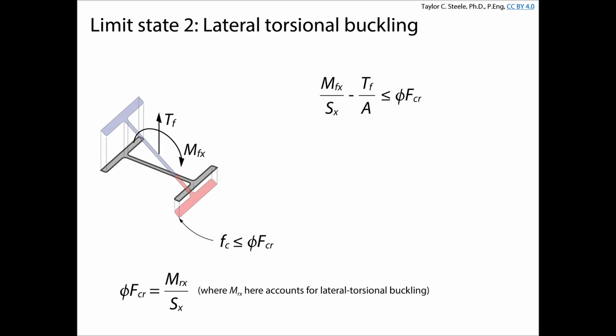Okay, so when we have lateral torsional buckling, we calculate MU, and for a class 3 section we calculate MY, and then MR might be phi MU, or MR might be 1.15 phi MY times (1 minus 0.28 MY over MU), or something like that.